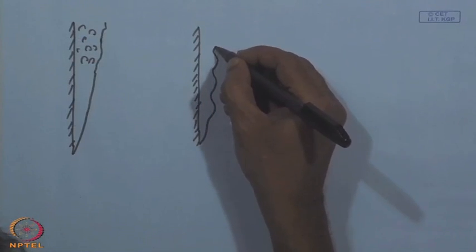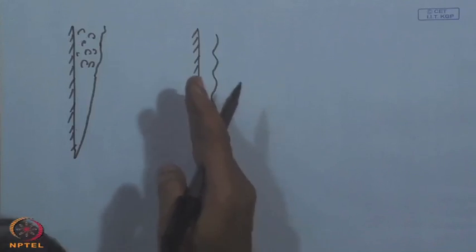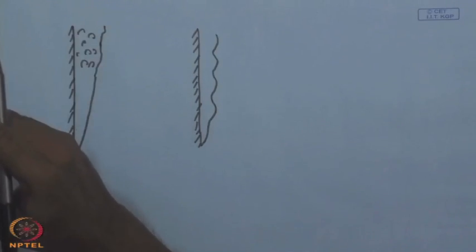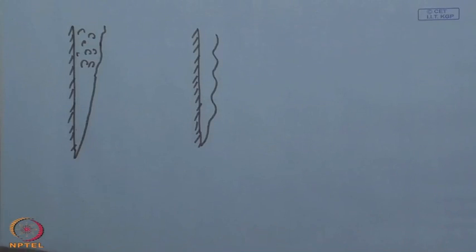As I have told, there is Kelvin-Helmholtz instability if there is relative motion between parallel layers of fluids, so due to that there will be undulations. These undulations will of course increase the heat transfer to some extent, but at the same time they make the analysis more complex. So, there are issues in film boiling which cannot be captured with the simplistic analysis which we have shown. There are issues like other complex geometries, and the effect of fluid motion. So, this is just a beginning.